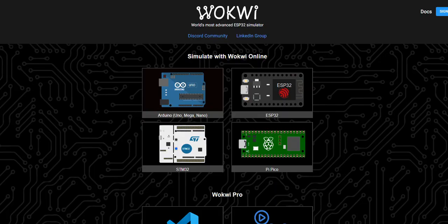One of the advantages of Arduino is its modularity. There are countless sensors, shields, and modules available that you can connect directly to an Arduino board. These include temperature sensors like the LM35, the DHT11, gas sensors like the MQ series, and wireless communication modules like the ESP8266 or an NRF24L01. You can use jumper wires and breadboards to quickly build and test prototypes, and you can scale up with custom PCB designs when needed.